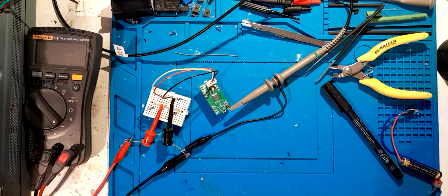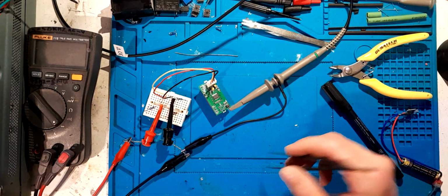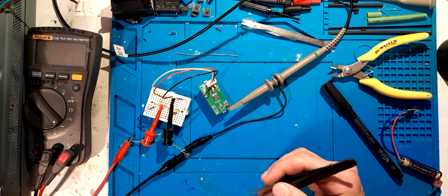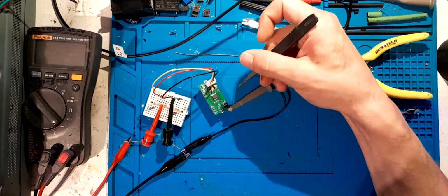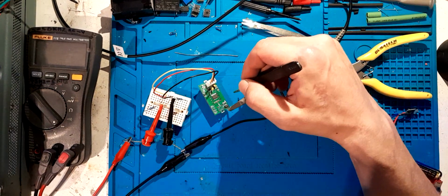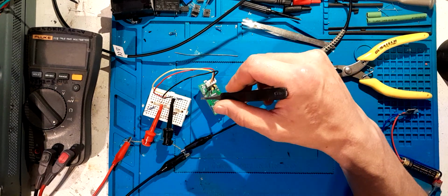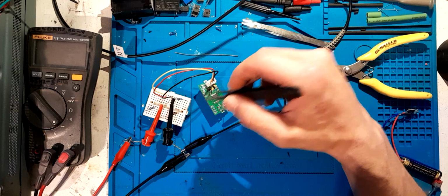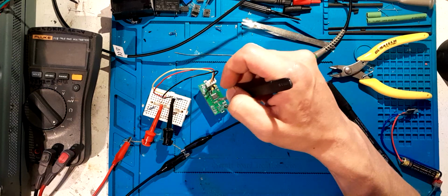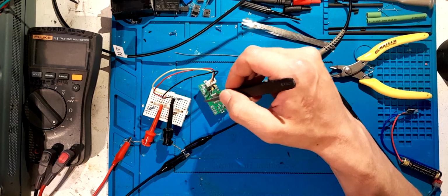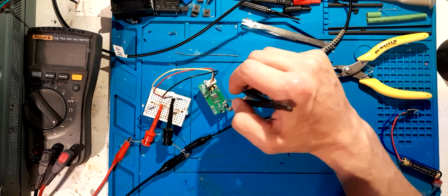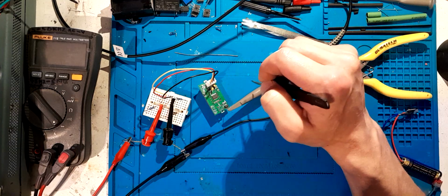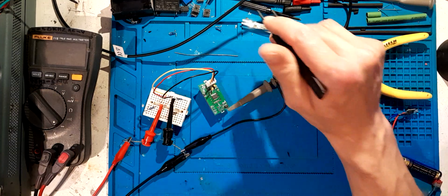Just something else that I wanted to point out. The reason why, even though I've basically knocked out all the oscillation, I'm still going to play not just with the regulator and its capacitors, and the VCC cap for the micro, the main voltage cap that decouples the positive terminal to ground close to the micro, and then the bulk cap near the regulator, and maybe even my input cap.